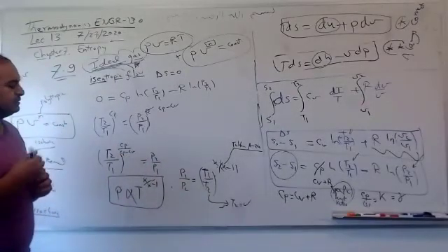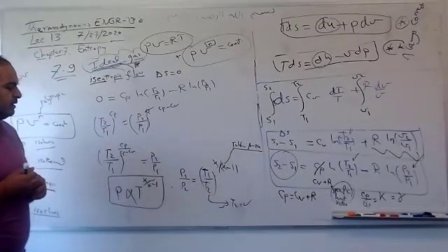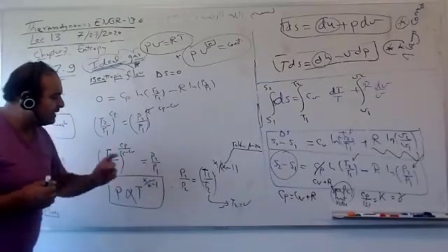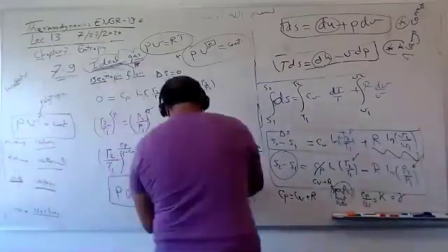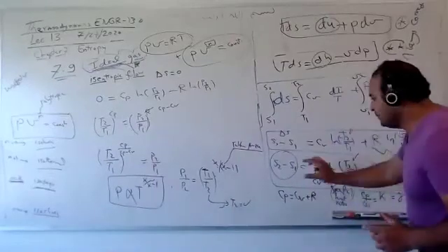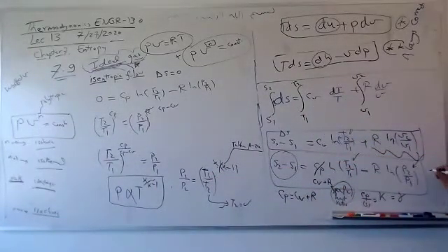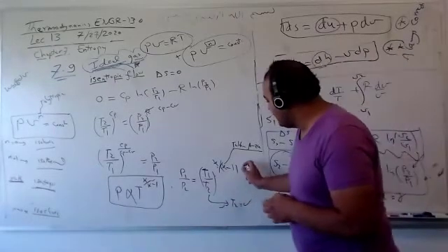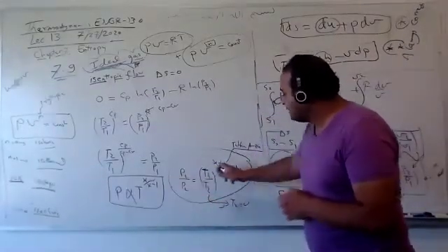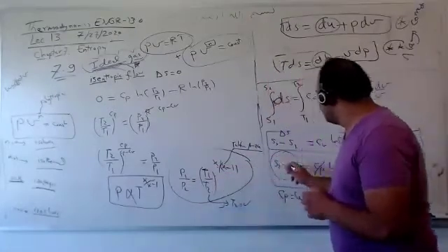Let's say 1000 Kelvin or something. So from this correlation, you can get T2. If you plot this ratio here, and you put this ratio of pressure here, of course, delta S will be 0, because this equation is called isentropic. It means I can obtain the pressure ratio and temperature ratio to make this 0.